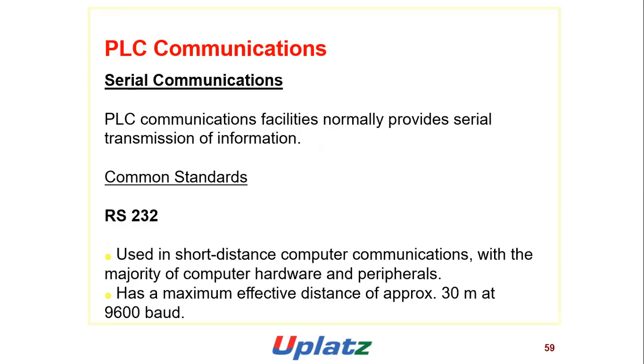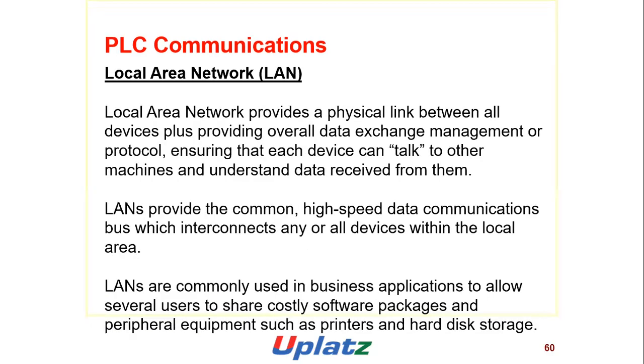Serial communication. PLC communication facilities normally provide serial transmission of information. Common standards: RS-232, used in short distance computer communications with the majority of computer hardware peripherals, has a maximum effective distance of approximately 30 meters at 9,600 baud.